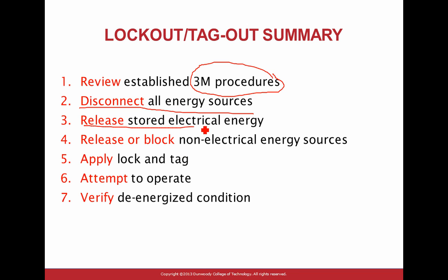And release stored electrical energy. Release stored electrical energy, guys. If you have a capacitor like this and you want to work on the terminals of the capacitor, you know capacitors are storage devices of energy. So you should know, based on the equipment you work on, that it has a capacitor, especially a power capacitor. These power capacitors typically come with a set of resistors. When you shut them down, it burns off the whole energy. So it has to release the energy out of the inductor or capacitor.